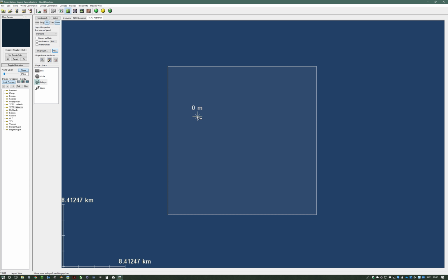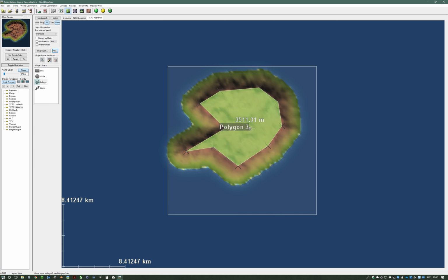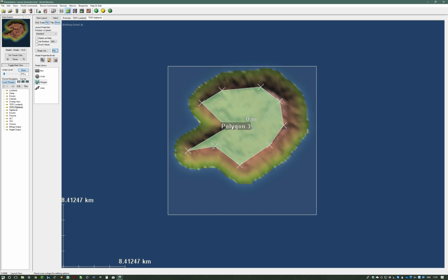The polygon is simply, you click on it over here, and then you get that little envelope-looking cursor, and you can just left click and create nodes in whatever shape you want. So let's do it like this, and then I right click when I'm done, and that gives me terrain in almost any shape possible. So I can just create an oddly formed piece of highlands,